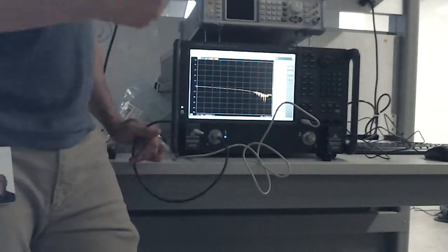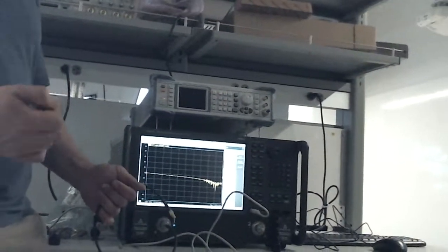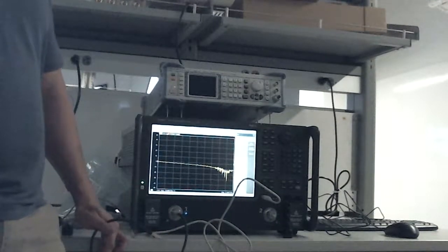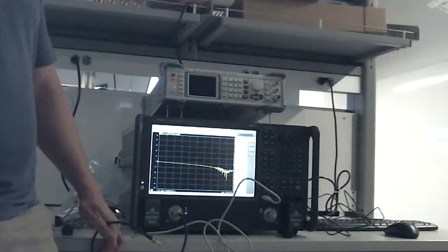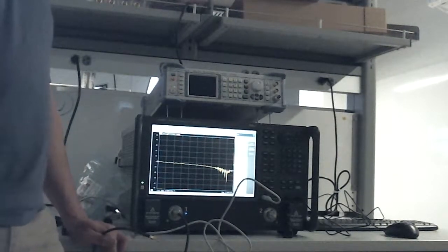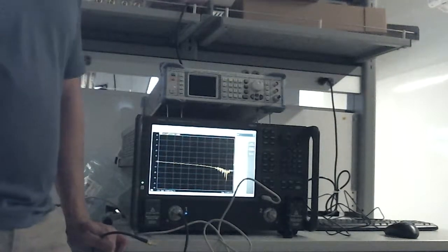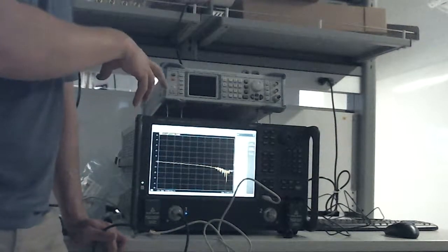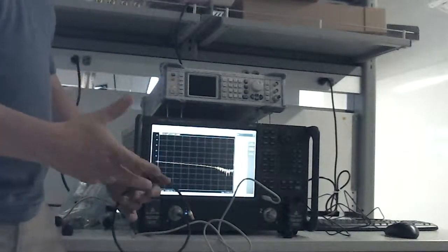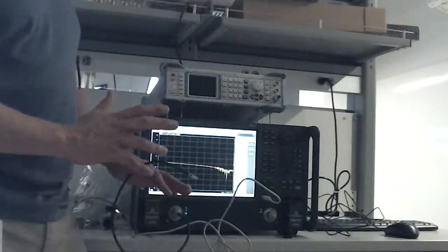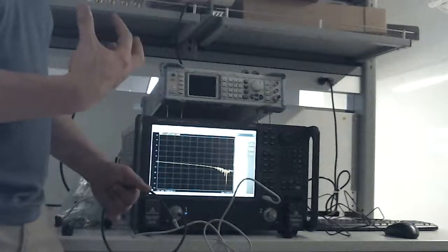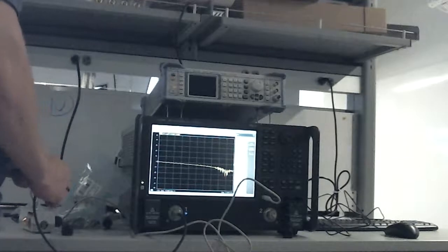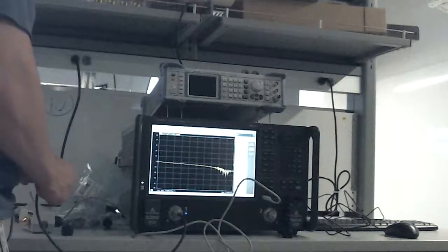If the phase of your cables and your whole measurement system is changing as you're doing your measurement, then the error terms that you initially measured when you did the correction are no longer valid as your system response is changing, right? So that's why you have to use really, really good cables attached to the network analyzer. Beyond that, the system response is going to be very well characterized, and all you're measuring really is your device. So let's take a quick look at doing this calibration and getting a feel for it.